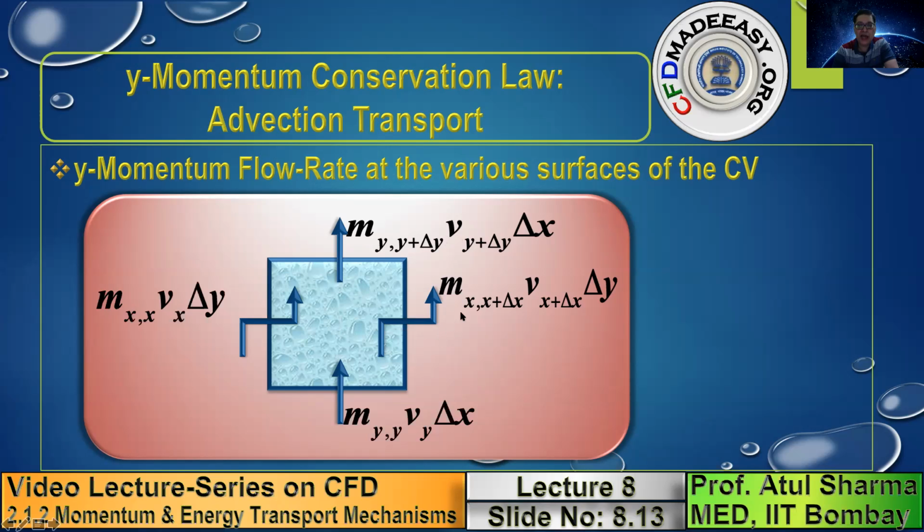Whereas we show zigzag arrows when the mass flux and the passenger, which is the v velocity, are orthogonal to each other. However, the final direction of the arrow corresponds to the passenger, which is the v velocity, due to the fact that the mass flow rate is a scalar quantity.